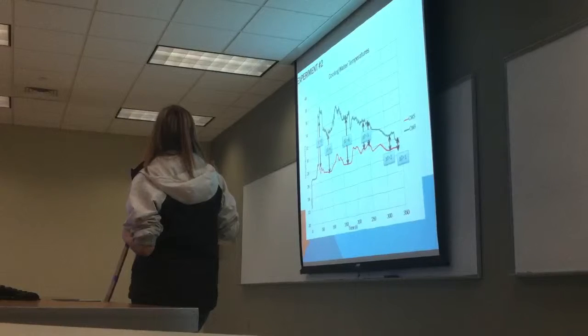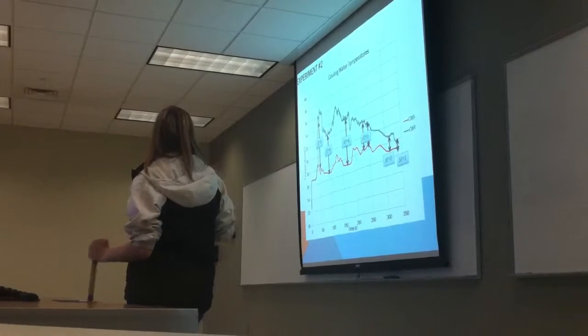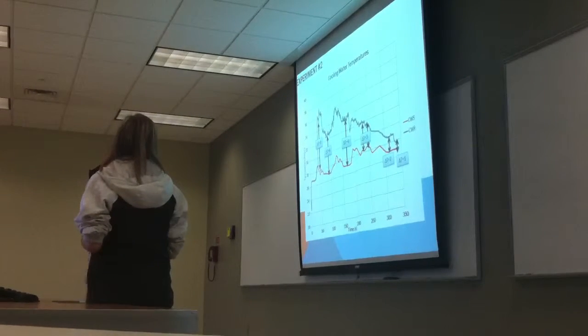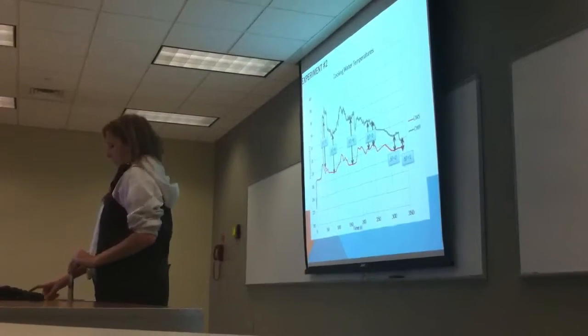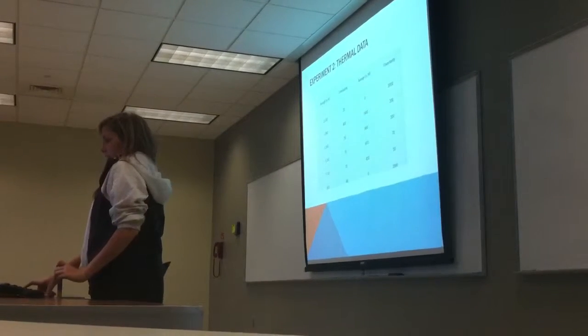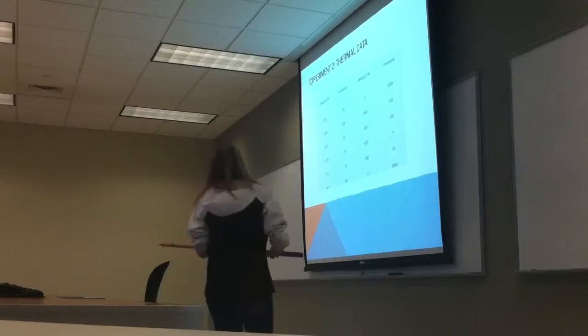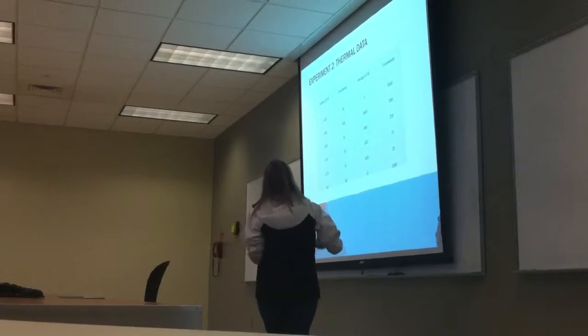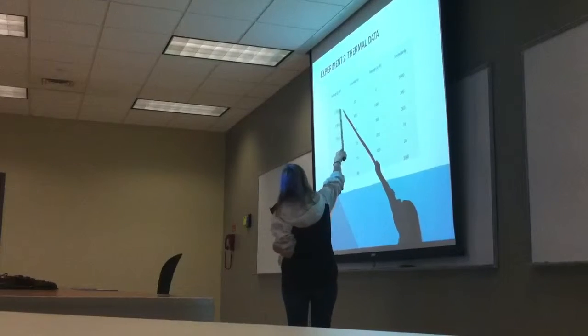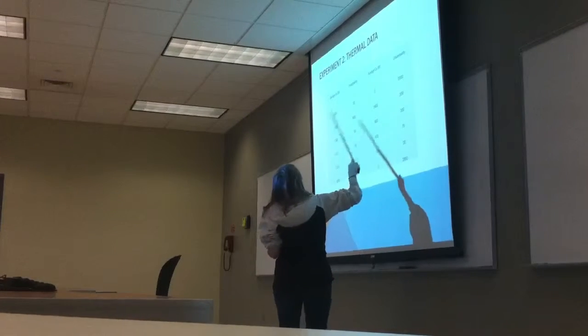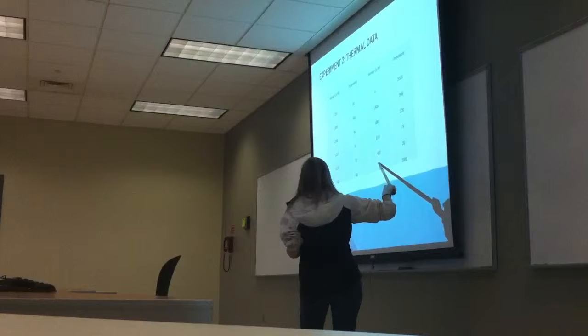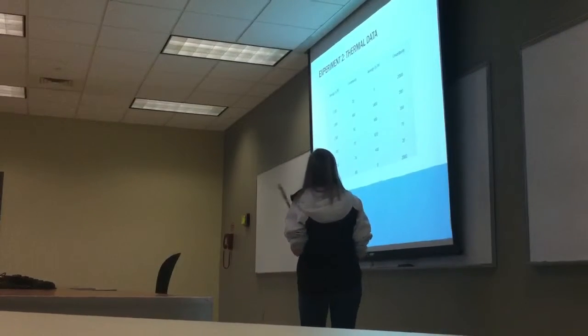where we decrease the reboiler power setting, so you can see all the delta T's for the different peaks. And the thermal data again, you have your average heat removed, and then your reboiler. So this is at the different settings that we set it to, and then this is the average heat removed from the condenser, and then uncertainty in both.